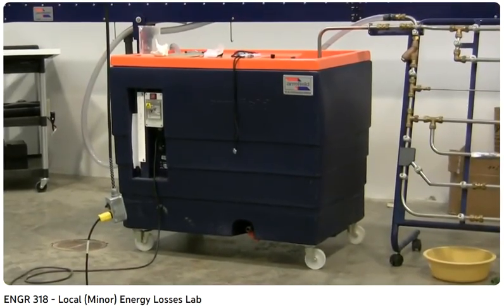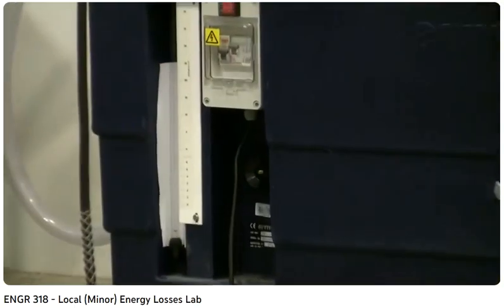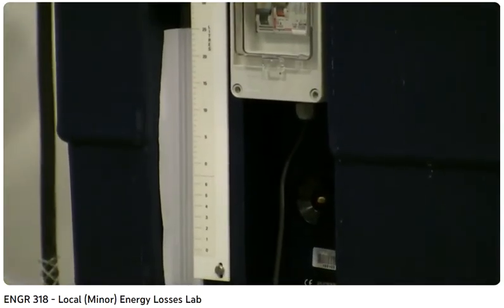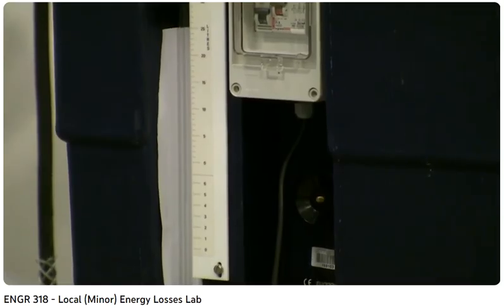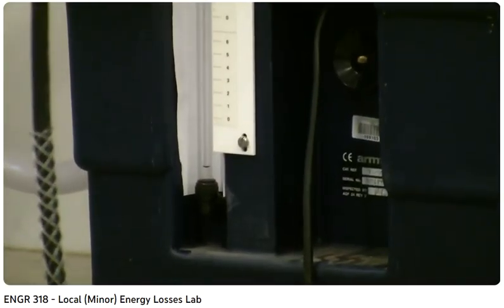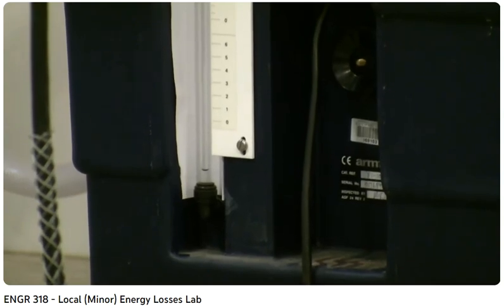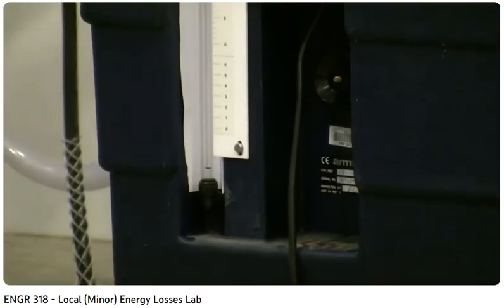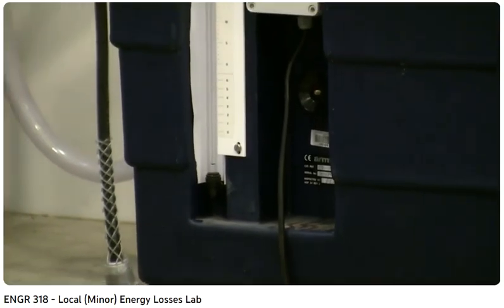The way that flow rate is quantified on the hydraulic bench is that there is a tube that indicates the level of water in the wet well in the hydraulic bench, and so the water level will rise in the tube, and the time that it takes to accumulate a certain volume inside of the wet well will be noted, and that is how you quantify the flow rate.